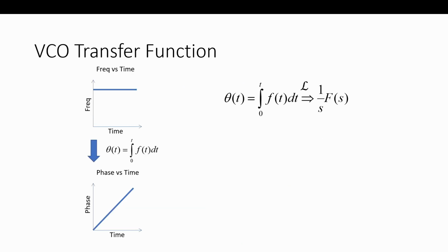Now, a little confusing because an integral shows up, but the takeaway is what I said before, that phase is the integral of frequency. I explain it better the other way, that frequency is the derivative of phase, and you can just clearly see it as a change in phase over change in time. And if we go back to the whole spinning phasor and the bicycle wheel, e to the j omega t, you see it there. If that bicycle wheel is spinning at a constant rate, that's a constant frequency. The phase versus time is changing at a constant rate. A phase ramp would be a constant frequency, right?